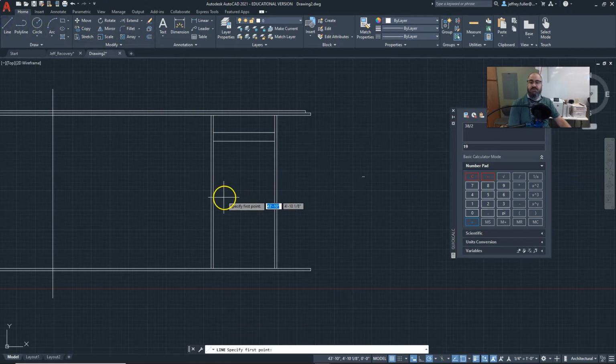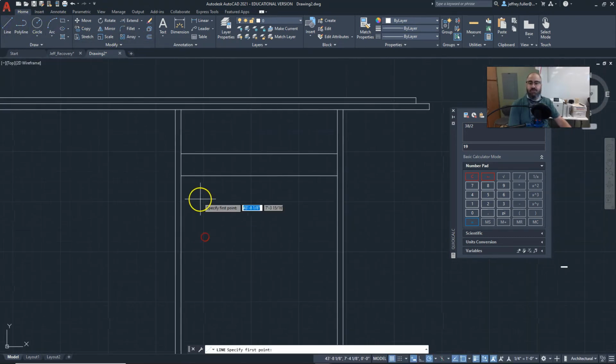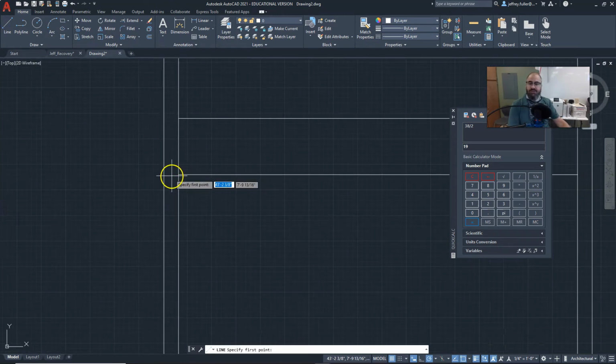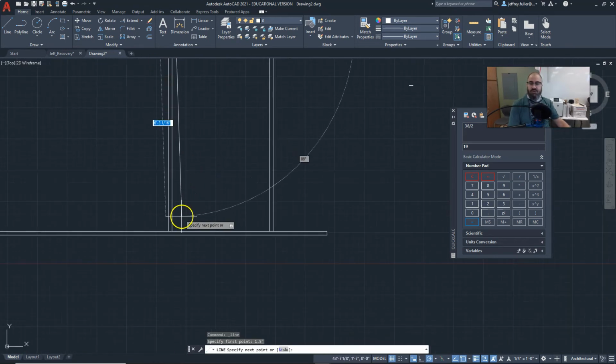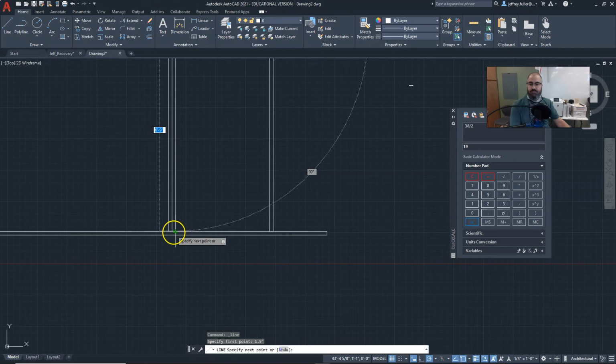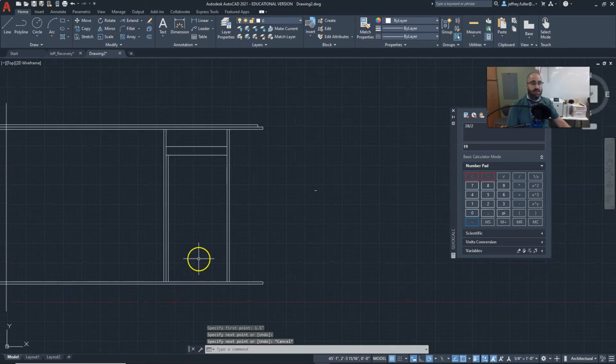All right, now I'm going to place some trimmers. So I'm going to go to a line tool. I can either offset this or I can just draw it. Okay, so I'm going to come in here, find that corner and drag it before I click. I do not click yet. Type in 1.5 inches and then hit enter, and that gives me 1.5 inches over is where I start my line. Okay, then that's my trimmer stud.